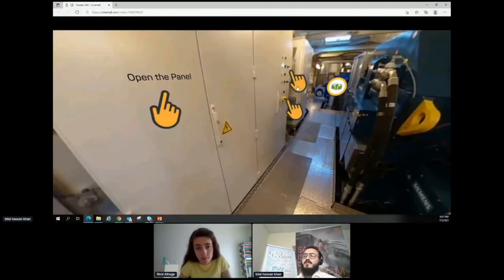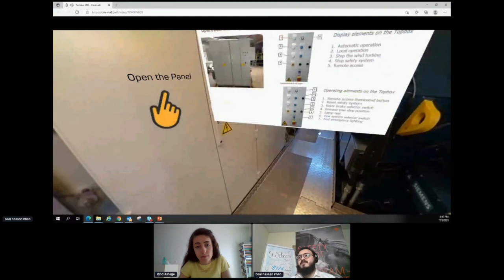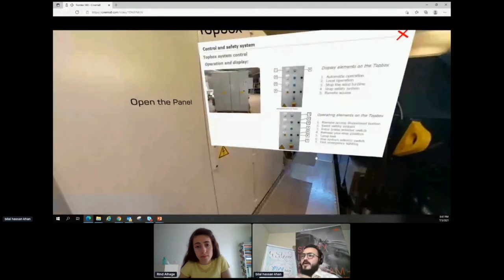As we have seen, there are some lights on the bottom side. The same system we have in the nacelle. We can use this system to control the turbine from the nacelle. If you don't have a laptop to connect with SCADA, then you can use these buttons and lights. These will give you some information about our turbines. What is the condition of the turbines? In which state the turbine is right now. You can also reset the safety system and use other functions with the help of these buttons.